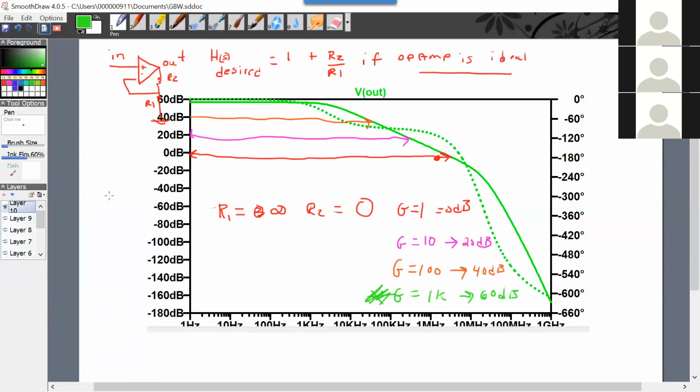Now, this graphical analysis can work for the inverting stage as well. Okay. And the magnitudes would still be the same, so if you had a gain of -1, you'd still have 0 dB. -10, 20 dB, right? The phase would be different. But in practice, though, it rolls off more before you get there. But really, it's a good estimate that you can use. Say graphically, where would this behave as a gain stage?